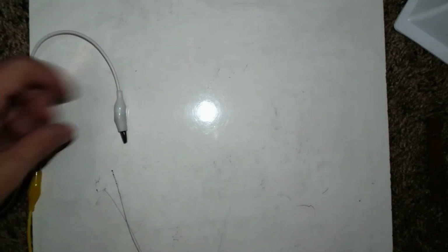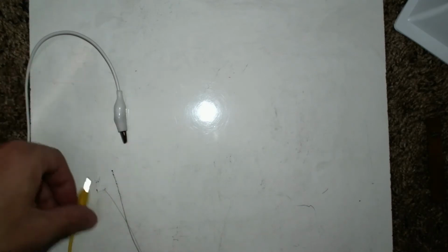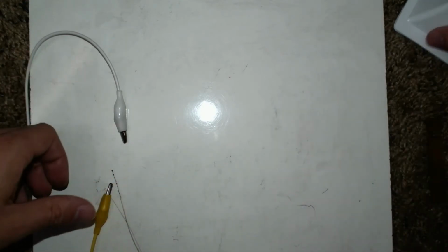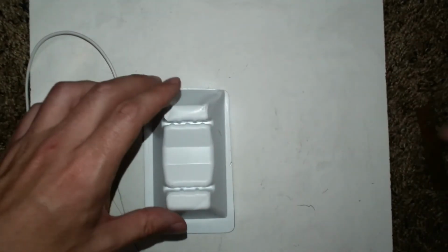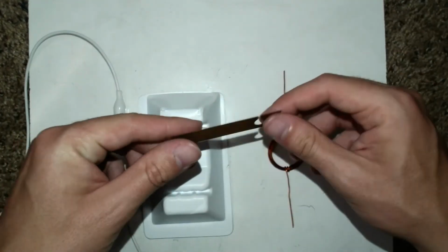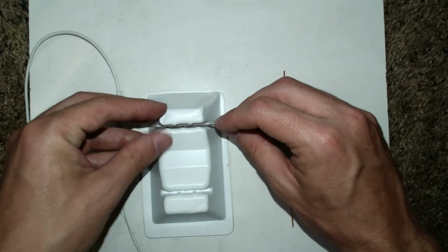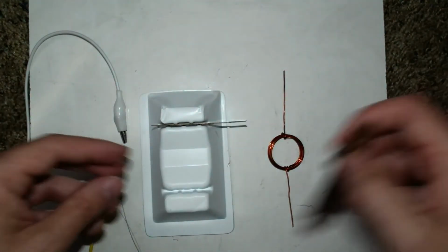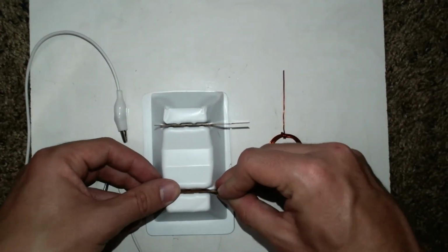So let's go ahead and build an electric motor from scratch so we can see how things work. What I'm going to need is two electrical cables that are hooked up to some source of electricity. So here I've got my positive and my negative side. And I need a coil of wire and something that can hold that coil of wire. In this case, these are copper plates. And I'm going to be using these copper plates because copper is an excellent conductor of electricity.